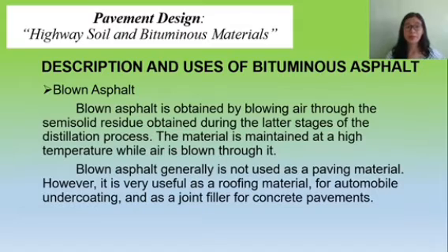Next, we have the blown asphalt. Blown asphalt is obtained by blowing air through the semi-solid residue obtained during the latter stages of the distillation process. The material is maintained at high temperature while air is blown through it. Blown asphalt generally is not used as paving material. However, it is very useful as roofing material, for automobile undercoating, and as a joint filler for concrete pavement.